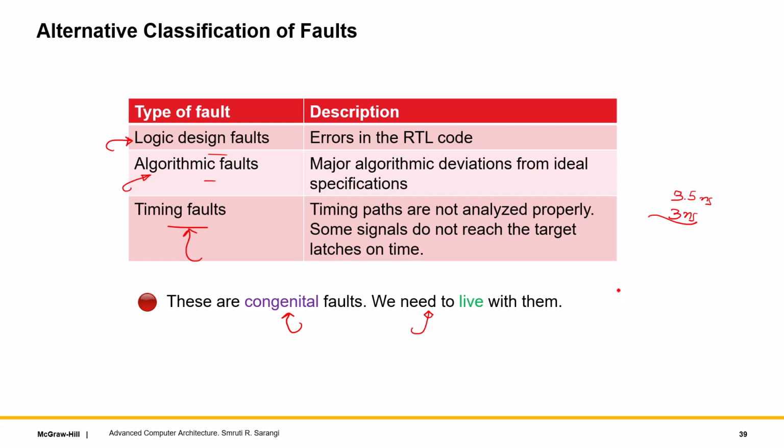In many modern research prototypes, a lot of signals are tapped, as I just mentioned, and you have dedicated what is called DFD hardware, design for debug hardware, that looks at these signals, computes functions on them, looks at potential buggy situations, and then either informs the user or tries to put the processor in a different mode such that these signals, at least one of them, is not triggered anymore. So some improvisation at that point is needed to ensure that we don't actually enter an erroneous situation.